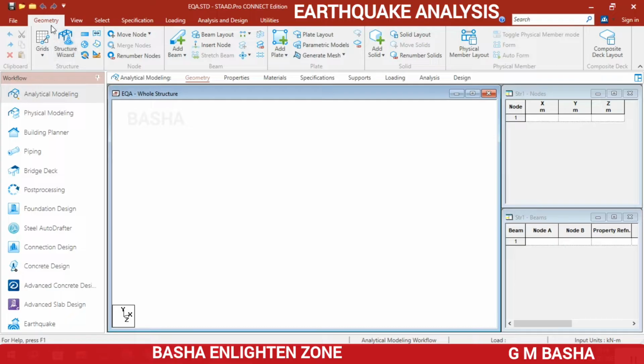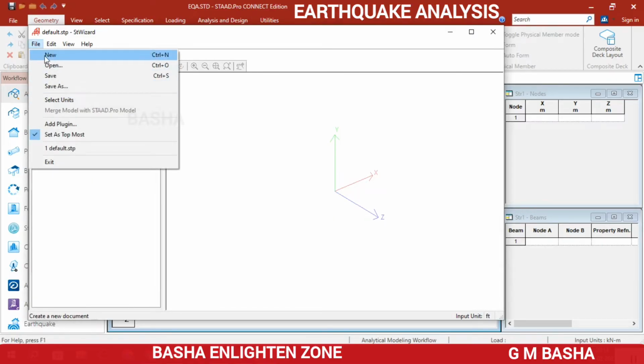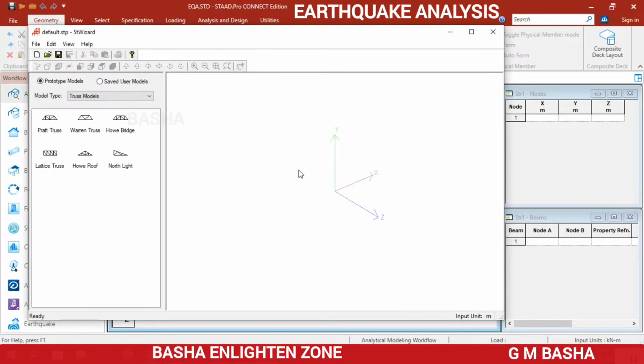Here in the geometry, select structural wizard. You will get a dialog box like this. Here first in the file you can select the units. In the file go to select units, and you can change feet into meters and then click OK. And then in the prototype models, by default it will be truss, you can change it to frame models and then choose bay frame.